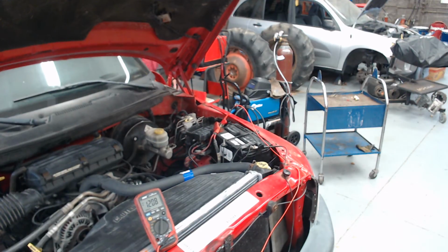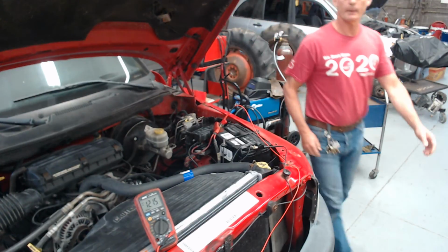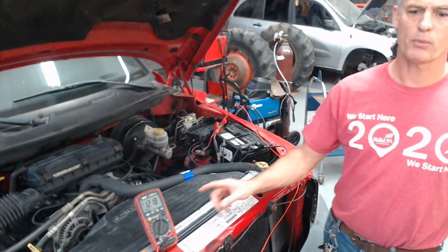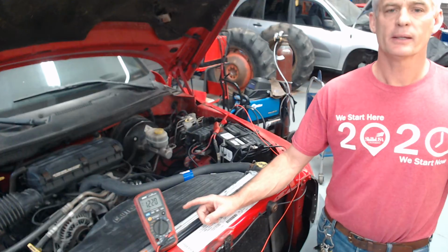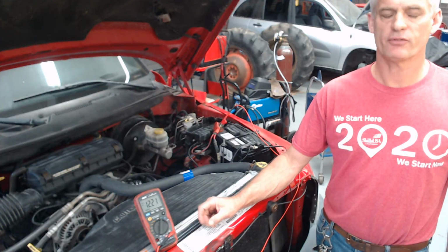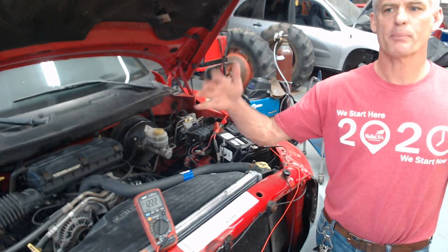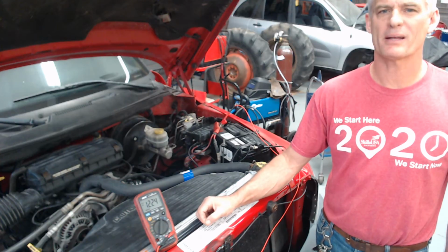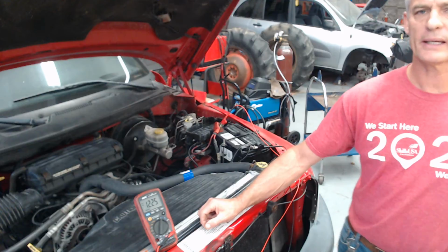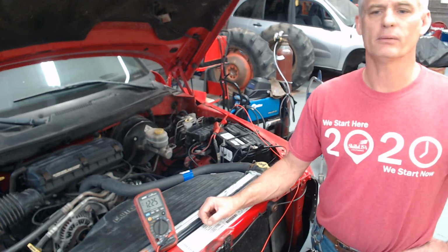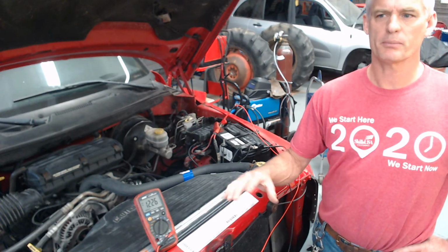So, as I said, it did fire for just a moment because there was still some fuel left in the ignition, in the fuel system, and it kind of went up, but it finally settled to about, I saw about 10.95 volts. So we would call that our cranking voltage. Anything between 10 and 12 is good, but usually it's going to be between 10 and 11.